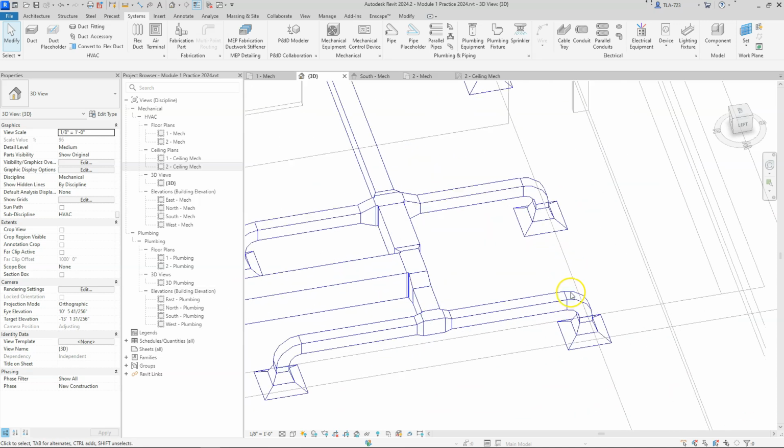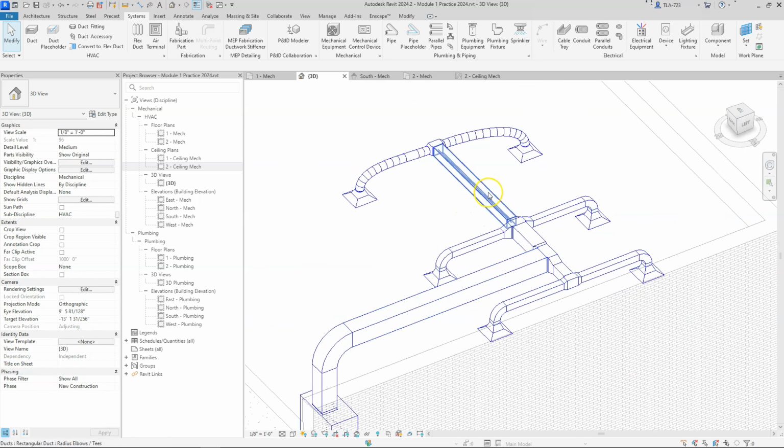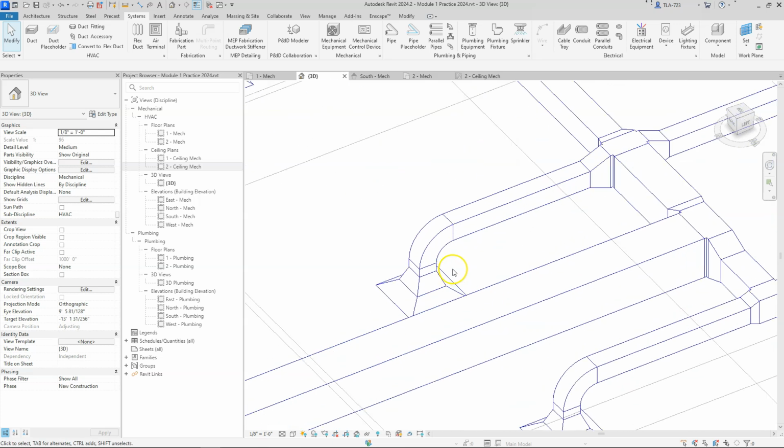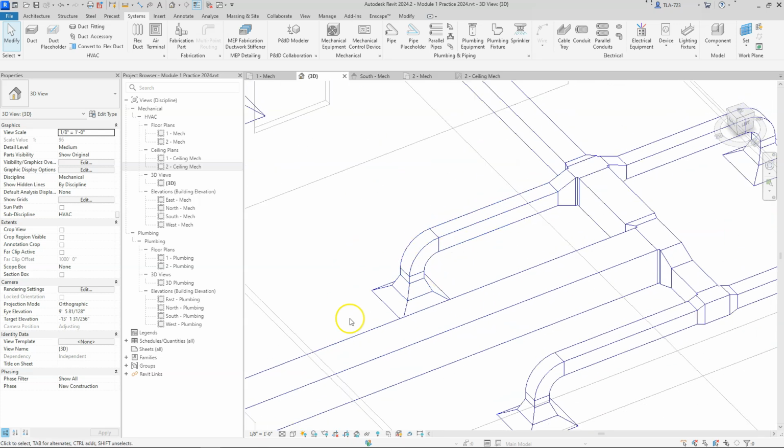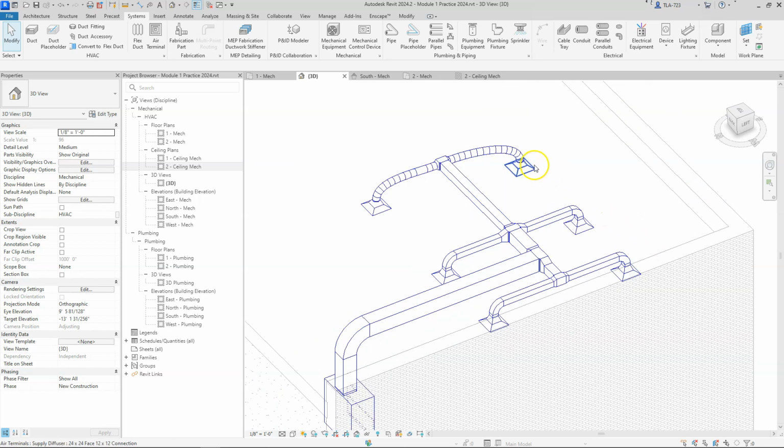The best thing you can do at this point is to just go through and play around with stuff, delete sections out and attempt to reconnect them with new ducts. Swap out the square with the flex duct like I did, see if you can get that to work. Try moving some ceiling diffusers around once it's connected. Definitely practice in having the system resize those ducts according to the airflow and the CFM associated with the diffusers.